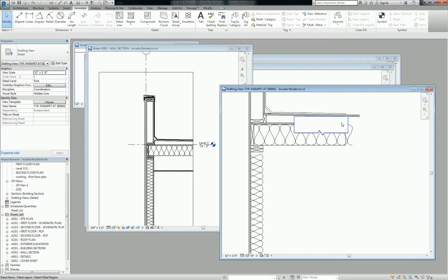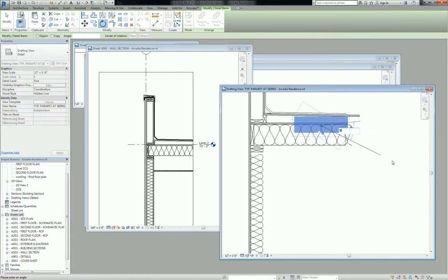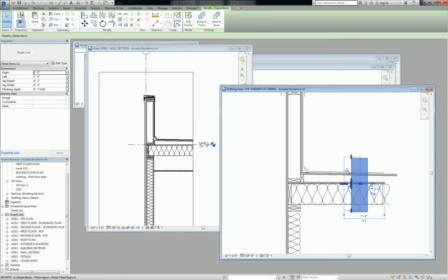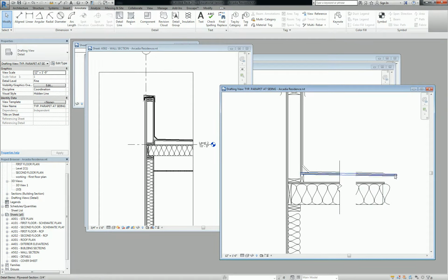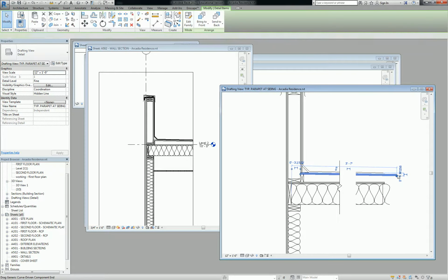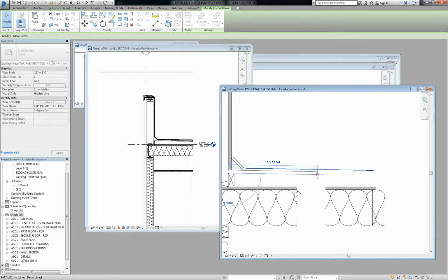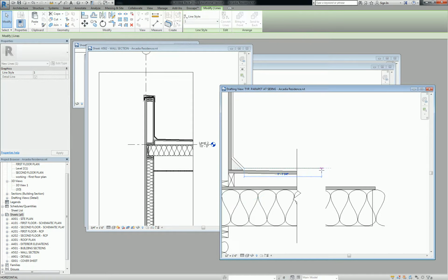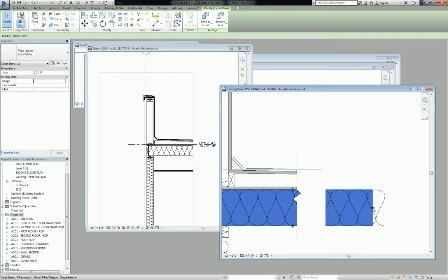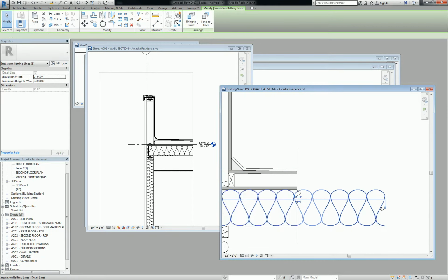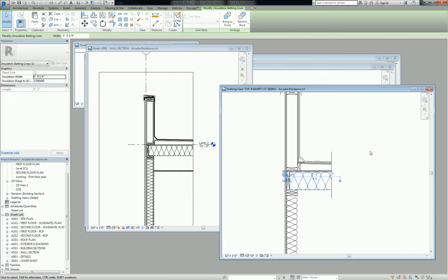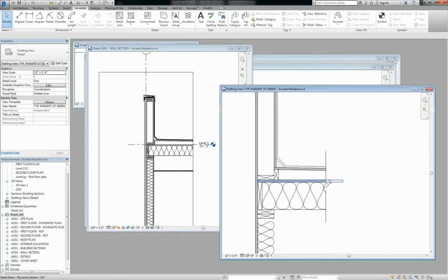So that mask, I can kind of just move it into place, and it'll mask things from that. I just need to select that, rotate it 90 degrees, put it wherever I need it, which I'm guessing will be right about here. And then all these other things, I can kind of just yank them into place. So I can pull this back. I can pull this back. Make sure you keep them from going back to parallel, or I should say 0 degrees. Now this is the laborious part, and this is where we actually spend our time anymore, right? Because you think Revit is so smart, all these things kind of do it themselves. But you still have some drafting type things that you have to do, and this is one of them. So anyway, that's how a break line works.